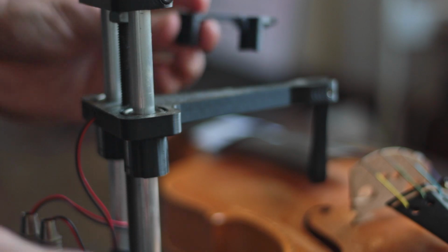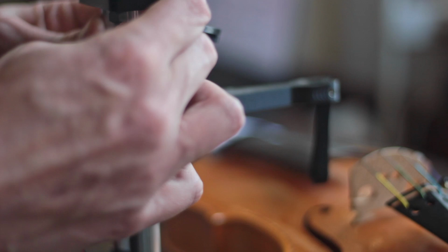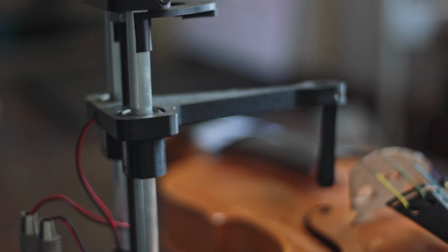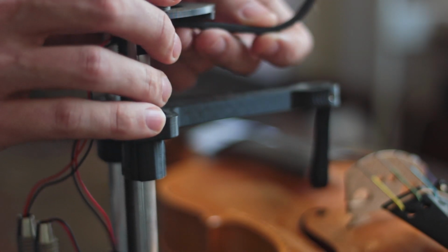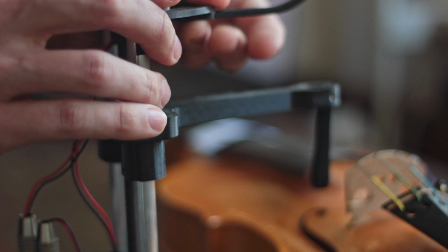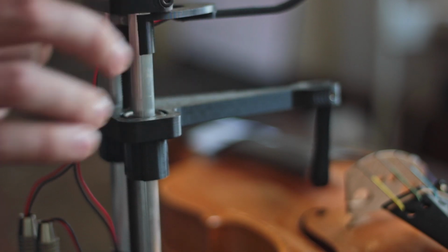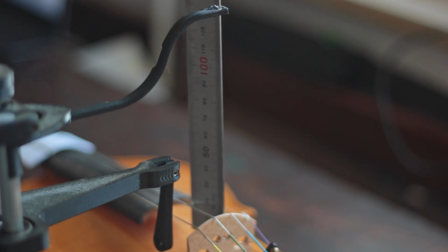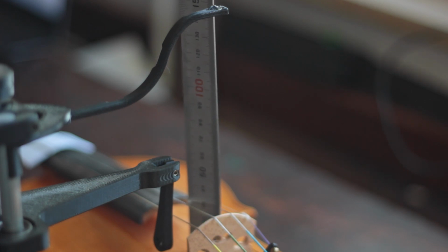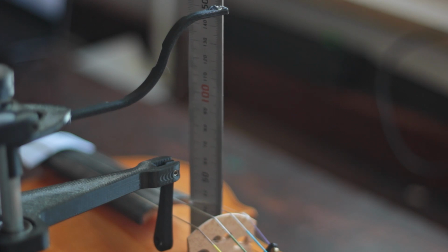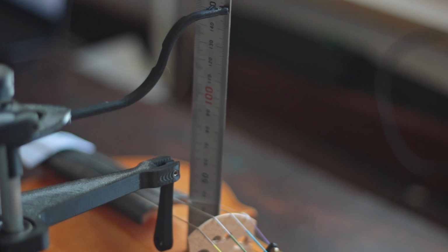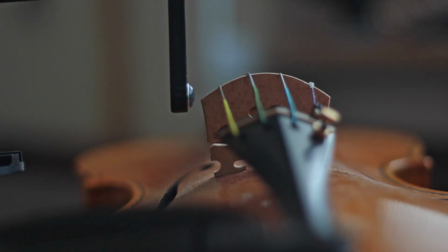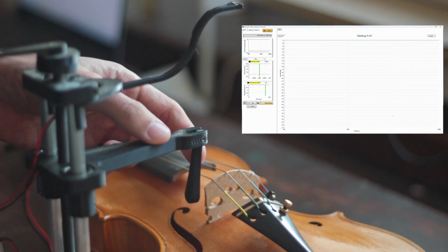as shown here. For this to work optimally, the slider should be installed so that the linear bearings are pointed downwards. Now clip the microphone arm to the microphone holder with the microphone pointed downwards. If you want to do repeated measurements like this and be able to compare them later, you will need to decide on a standard microphone distance. Here I adjust the distance from the top plate to 150 mm. Now, as before, we can position the hammer and take the measurement.